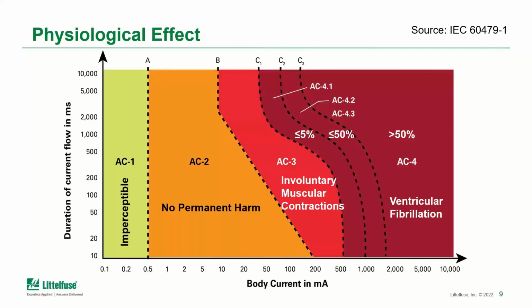So this is just something to remember as we keep talking about some of the other slides. In particular, the standard household GFCIs trip at 6 milliamps or below, and this value is not selected by accident. Just as I mentioned, with those Class A GFCIs we want to stay below the let-go threshold, which is why that value of 6 milliamps was chosen.